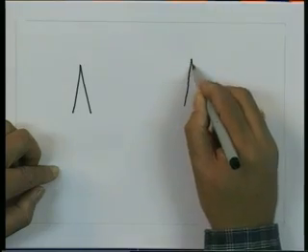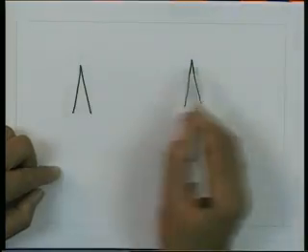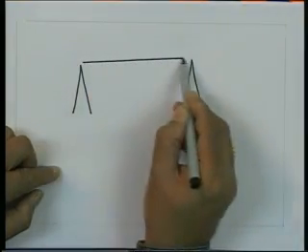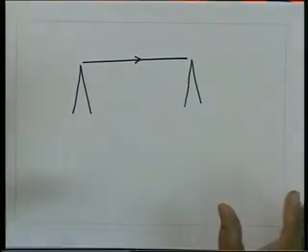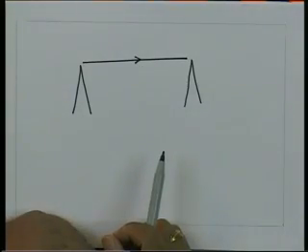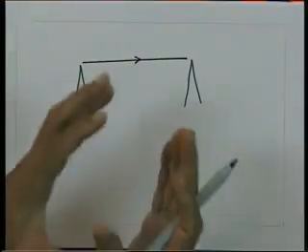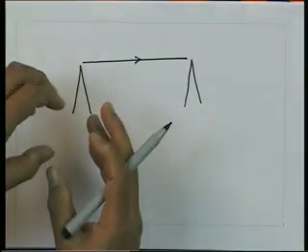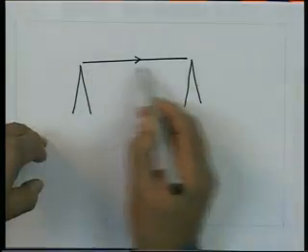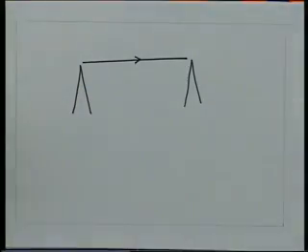Let us say I want to establish communication between 2 points, as we do for example in microwave towers which we see around us. So, I have a microwave tower here, I have a microwave tower here, and the interest is essentially to send the power from this location to this location with as minimal loss as possible. In this case, I would prefer to have an antenna which will be highly directional. That means this antenna should put power only in this direction and should not give the power in any other direction.